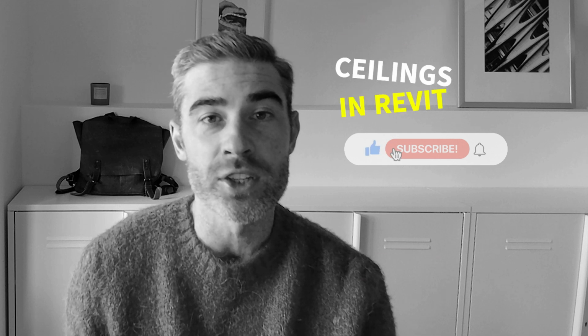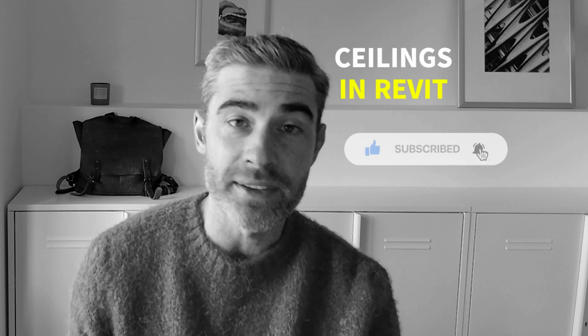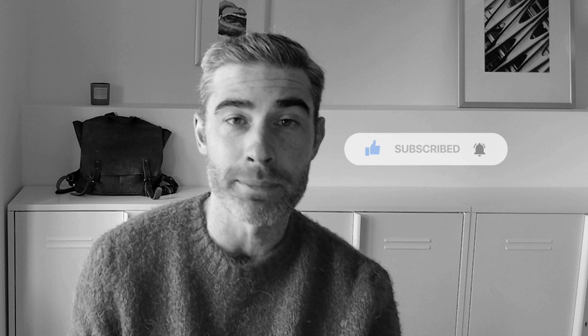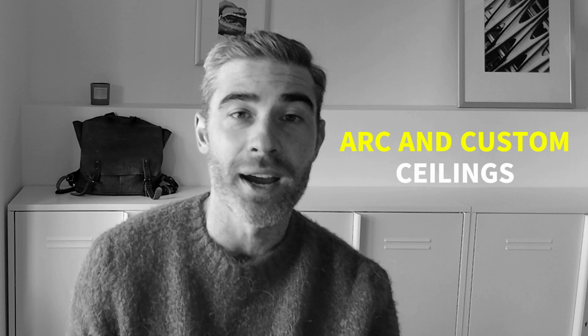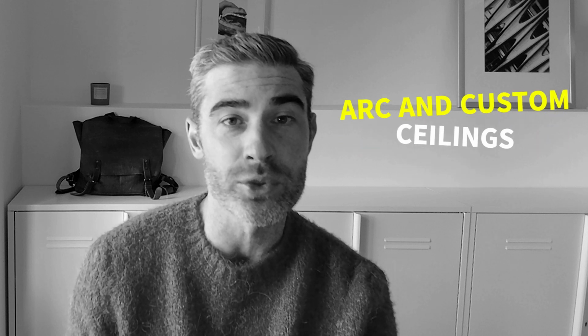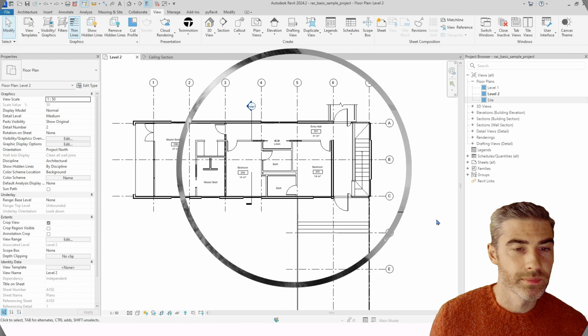And today we're talking about ceilings. Everything you need to know about ceilings, from how to place them, how to edit the assembly to make the construction and the type of ceilings that you want to place, but also the types from generic flat ceilings to potentially adding a slope to that ceiling, or maybe we want to create arcs and organic shapes. And I'm going to go over today how to utilize those tools and how to get to that end finished result. So let's jump right into this week's episode on ceilings.